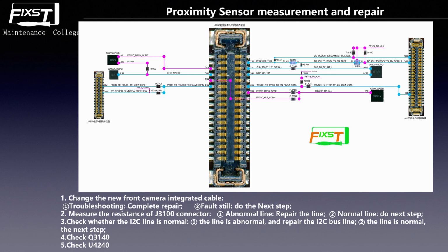Okay, after we study the display circuit, we study the backlight circuit. If the phone has a problem only in the backlight circuit and the display circuit has no problem, when the phone powers on we can see the logo, but not very clean. If you can see the logo, it's okay but not very clean, it means that the display circuit has no problem, and the problem is in the backlight circuit.